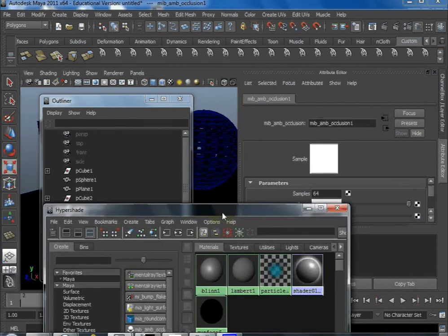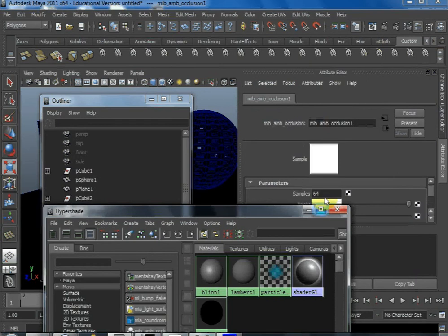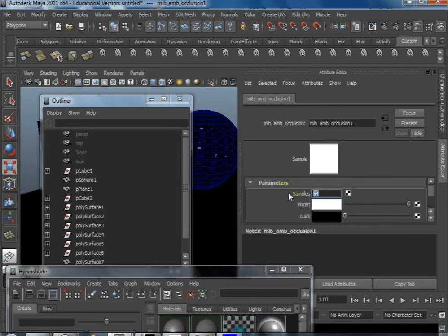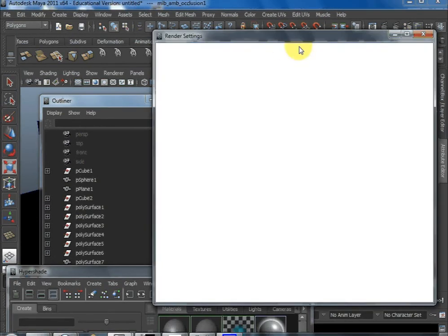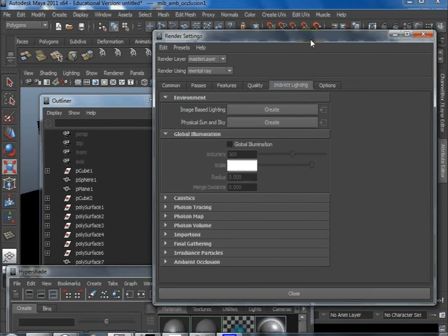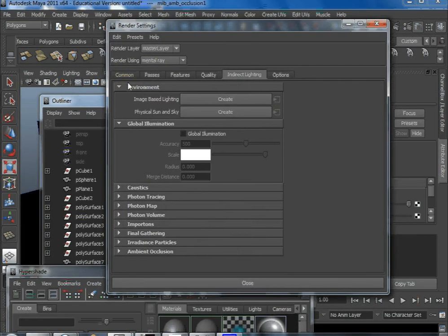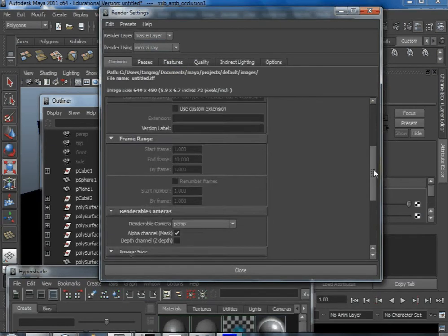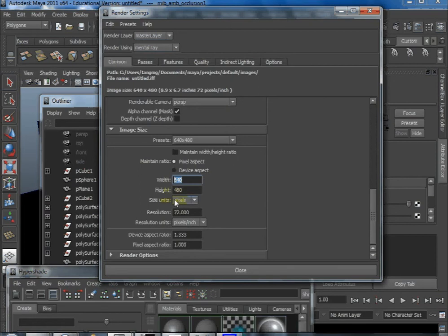Yeah. There's another thing. Besides the samples, I think it will increase the rendering time. Just be aware. I would just go 128, even higher than that. Okay. At the same time, I know the quality is also controlled by the resolution, right? That's typical for Revit, for whatever software. You know, the higher quality, the more pixels you have, it looks better, right? Exactly the same.